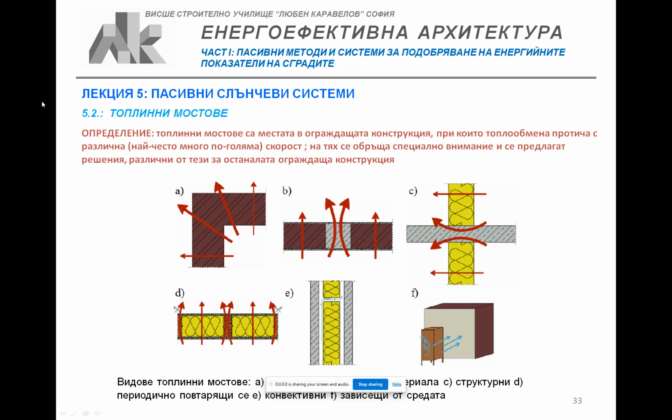The thermal bridges can be material thermal bridges when the material is the same but we have an edge, changing of the direction the element goes, and in that place a single measure unit of the inner surface has much more outer surface that radiates the heat, and that's why in the edges of the buildings the heat loss is more than on the other parts of the elements.